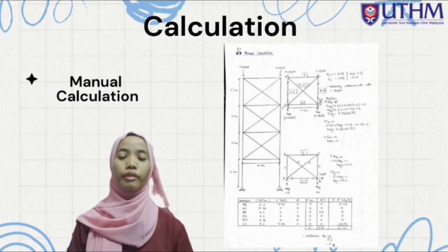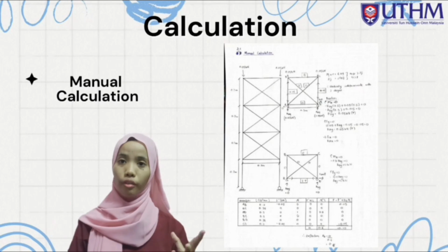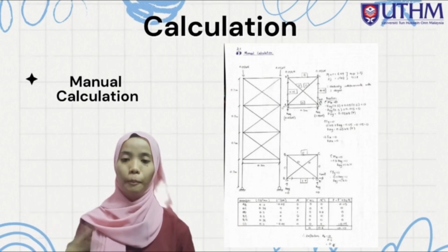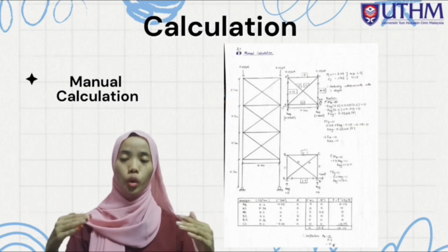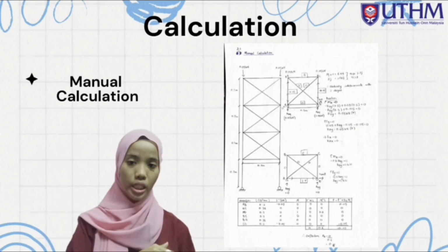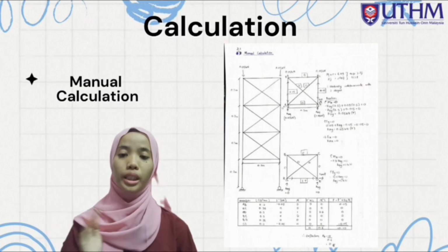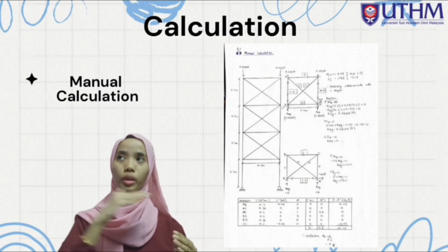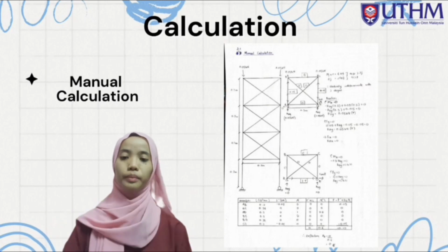For internal force, I found that member AB is negative 0.05. Why negative? Negative because the force is compression. If compression, the load is negative. For member AD it is 0 because there is no load from the X axis. For member DC, 0.05 compression. Member BD and member AC are also 0 because the member from the axis is 0 and there is no load for the hypotenuse.